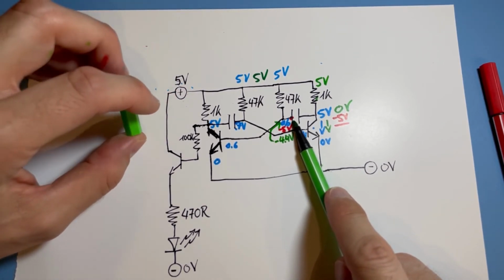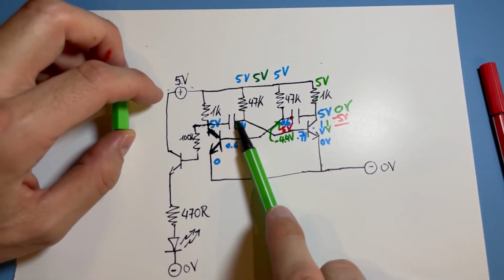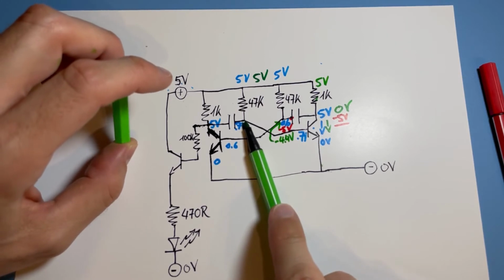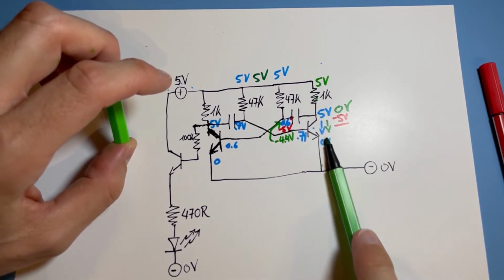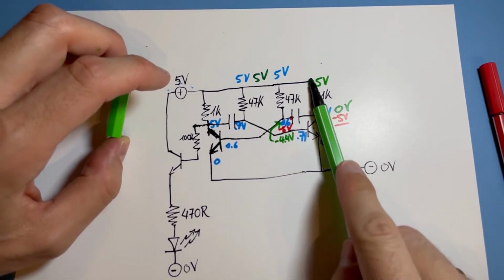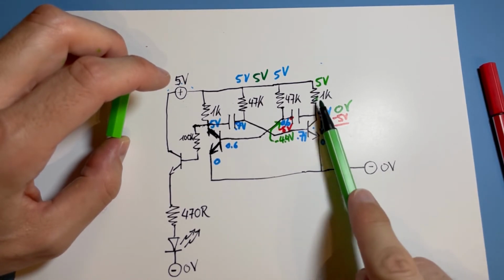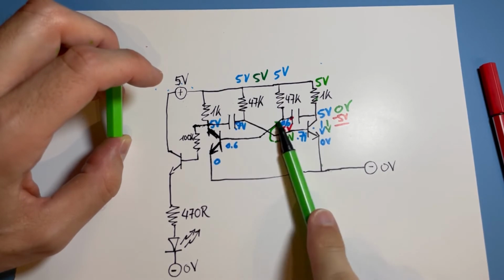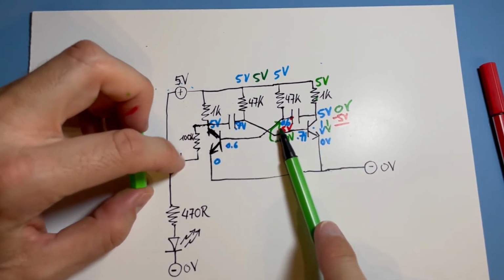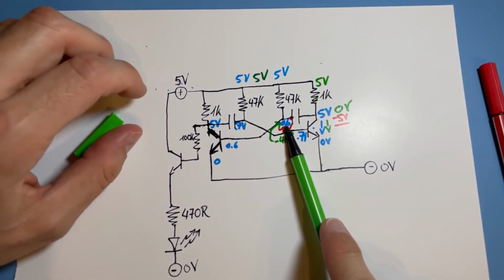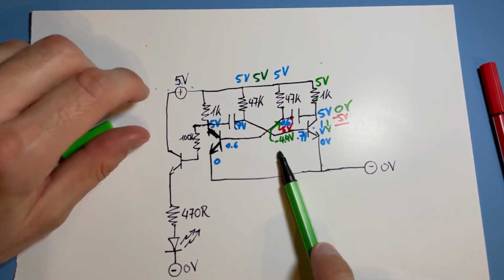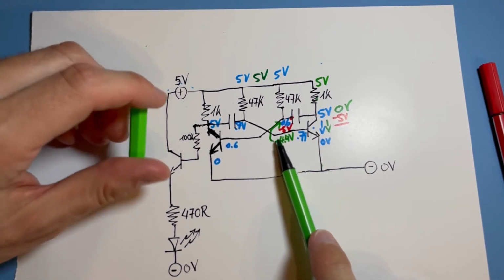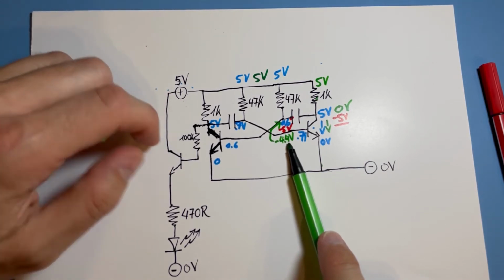And so that's the winner situation. This capacitor was first charged to 0.7 volt. It led the transistor to a conducting path. And that conducting led to a drop of 5 volt here, and that leads to a drop of 5 volt here. And now the small loser of 0.6 volt gets to be the big loser because now 5 volts are additionally subtracted, and now he is at minus 4.4 volt.